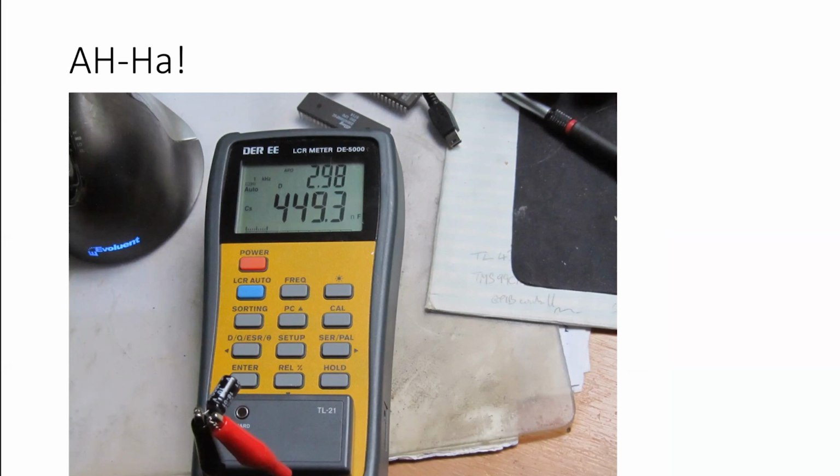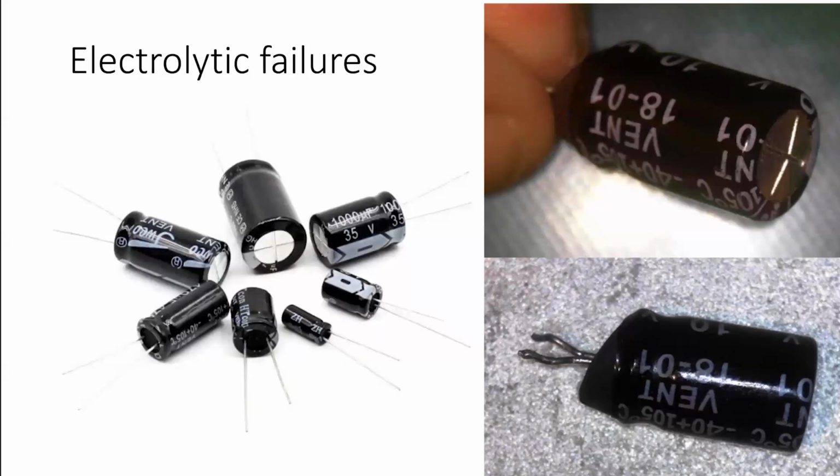Also, the other number on there, the 2.98, that's the dispersion coefficient. The dispersion, the ESR, the Q, everything that you could measure for this capacitor said this capacitor's dead. Forget about it. So let's look at some failed electrolytics.